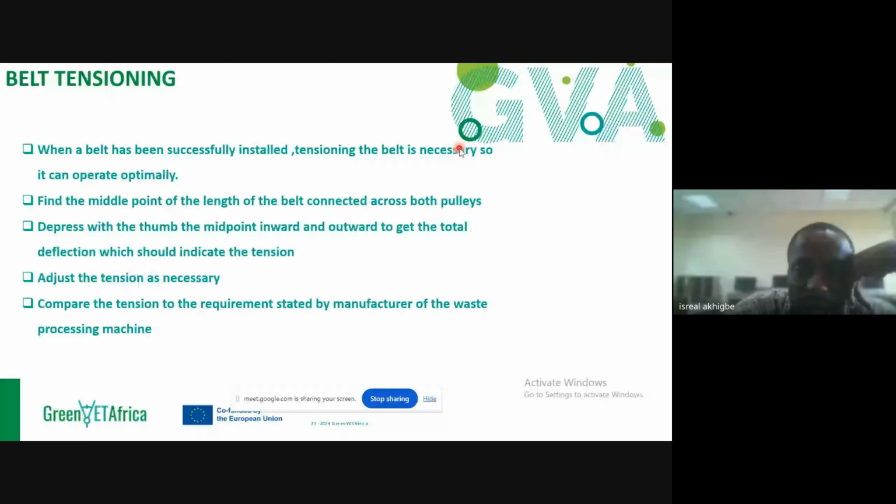the air. So when your belt also similarly has lost its grip and you are still trying to use it, remember that belts work with friction. It will start rubbing. So while your driver is rotating, trying to send motion, it will just be rubbing, making that striking noise that will be disturbing and hurting. Also, because of that worn out surface, tension will be greatly reduced because there's no way for it to grip properly on the pulley. So that's why we're talking about belt tensioning.